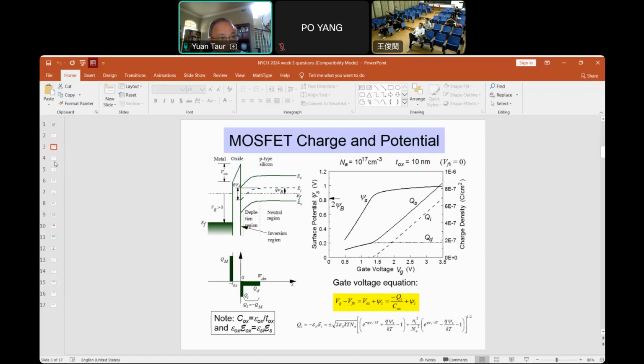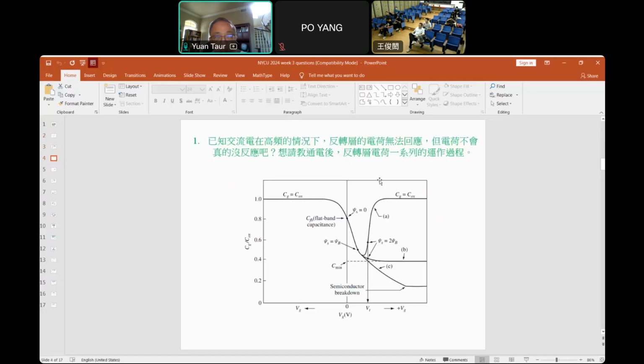Okay, but now that's for capacitance. But now, there's really no change. There is actually some change due to the inversion charge, but not the magnitude. In other words, for a fixed bias, when the AC goes up and down, positive and negative, the inversion charge will respond in such a way that the distribution will be different.